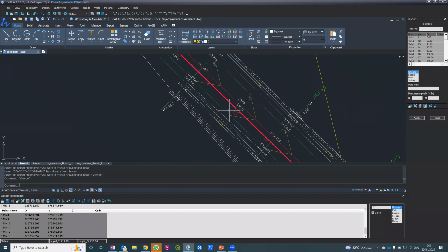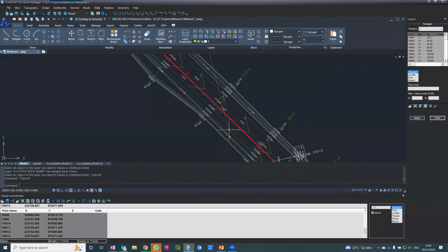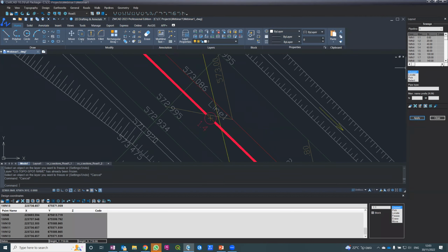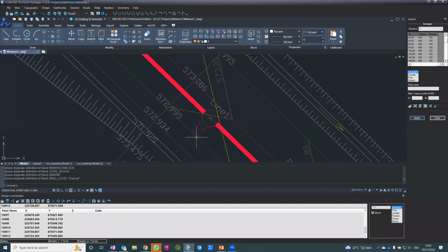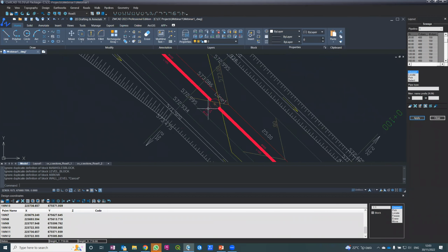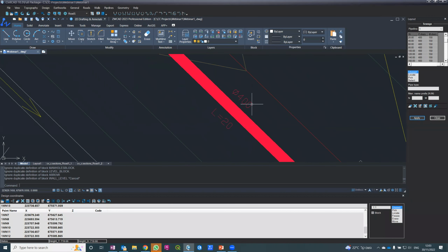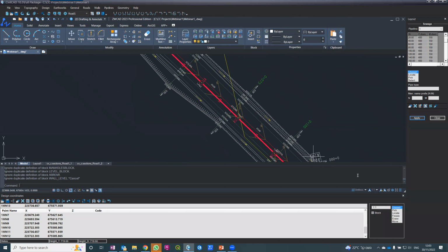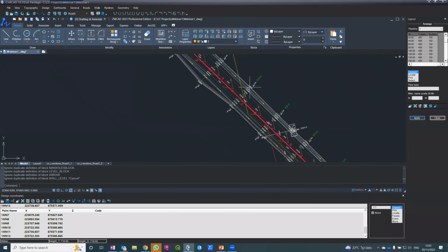Okay. But the issue is that I've not defined anything else. So I'm telling the software to take this and make it a 400 millimeter pipe. And for the manhole, use 150 cm, because this is the unit that I'm using for the manhole itself. So now you see the manhole became bigger, and this is 150, and we also see the data here, 150, and this is 400.